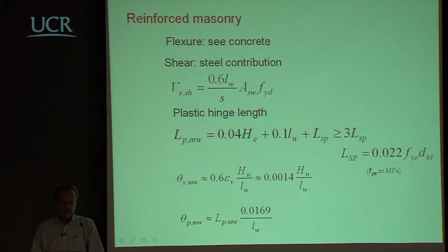For flexure, I won't say anything more because you take the same stress block that I was using earlier, and you simply add the tensile capacity of the steel. So it's something similar to what you do with concrete.